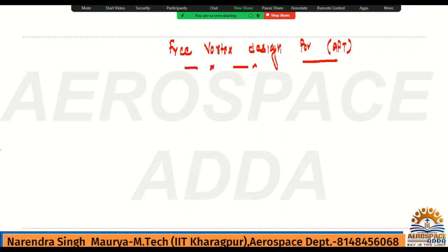See, what we have concluded, or what we have pointed out earlier, we had seen the velocity triangles, and it is varying from root to tip of the blade, because whatever the velocity at root, it will not be the same at the tip, it will be different. Remember, whatever velocity triangle we had drawn, we are considering the mean radius. For each and every point we cannot draw the velocity triangle, so whatever we had drawn is for the mean radius.